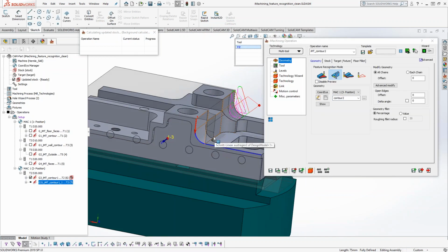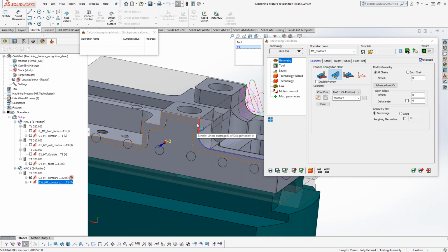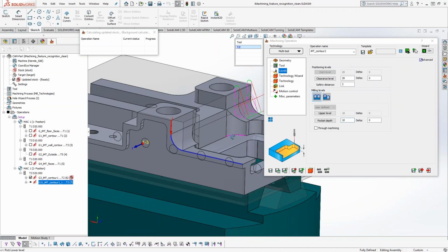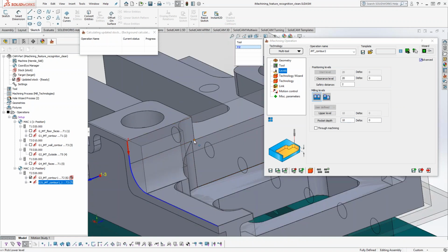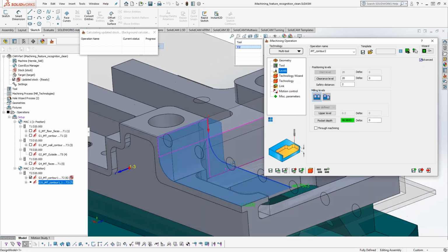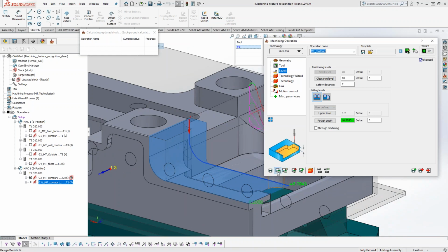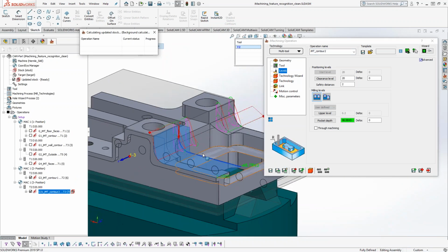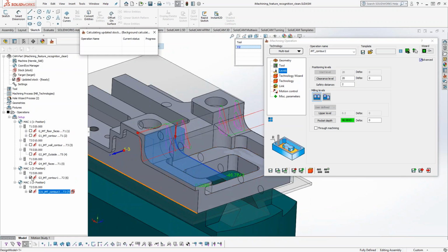These are things that I think we'll get better with our feature recognition as we go along, but it's something to pay attention to. I think almost everybody here is used to picking chains, so you're cutting on the left-hand side of the geometry, but just something to think about. I will pick this vertex, save and calculate. We got our toolpath. It looks good. I'm happy with it.